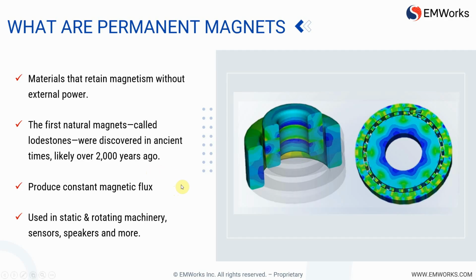Permanent magnets provide a stable magnetic flux with zero ongoing energy cost, making them ideal for passive or energy-efficient applications. In electrical engineering, they are usually used in motors, generators, magnetic bearings, and sensing devices. Their performance, however, is bounded by material limitations such as Curie temperature and mechanical fragility. Therefore, understanding the magnetic behavior and physical constraints of these materials is crucial for successful integration in dynamic electromagnetic systems.